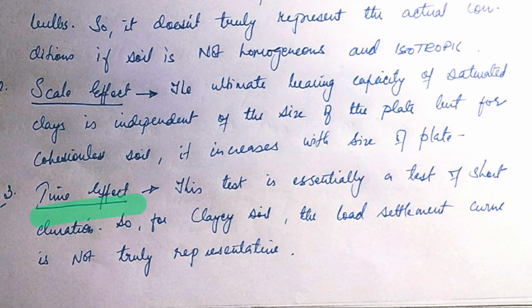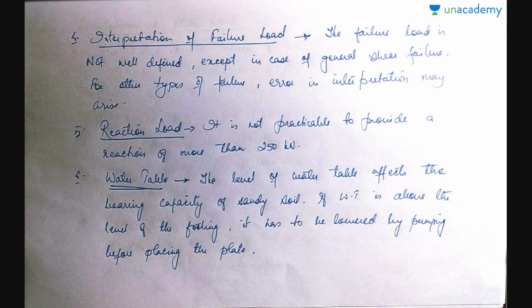Now, it has time effect. Time effect means this test is essentially a test of short duration. So, for clay soil, the load settlement curve is not truly representative. Why? Because clay soil takes a longer time for its ultimate settlement. So, the load settlement curve is not truly representative of the settlement that actually happens in a clay soil.